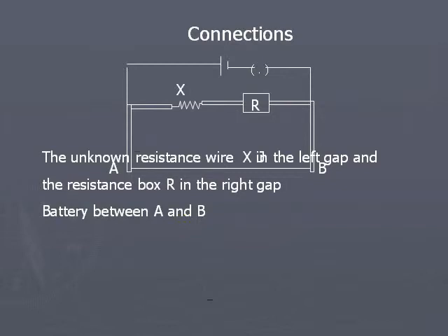The battery is connected across the ends A and B of the meter bridge wire in series with a plug key. A battery and a plug key are connected in series across the ends of the meter bridge wire AB. Then galvanometer, high resistance and jockey are connected in series from the point C. From the terminal C, galvanometer, high resistance and jockey are connected in series.